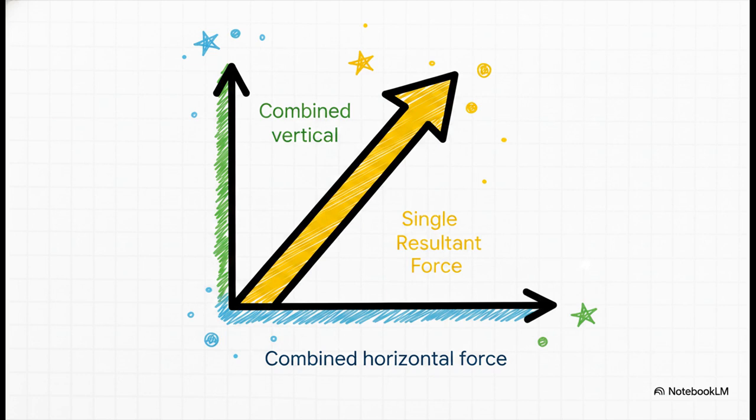And honestly, here is the real magic of Cartesian vector notation. Once absolutely everything is sorted into that I and J format, you just sum up all the I components together and all the J components together. The total chaos of three diagonal intersecting forces just neatly collapses mathematically into a single, clean resultant force equation. Our net horizontal pull comes out to 972.7 newtons, and our net vertical pull is 102.7 newtons. From there, tracking down the final magnitude is literally just running the basic Pythagorean theorem.